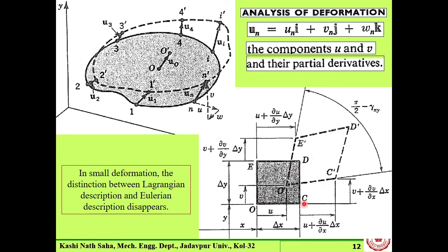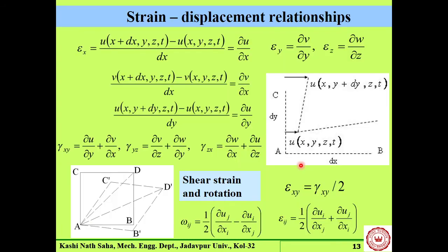From analysis of the displacement field, what we get is the length of this line and the length of this line, but the reference point has moved. So to measure the change in length, we have to shift point O prime back to the reference point O and then align it. Only then can we find the extension of the line to obtain our normal strain.